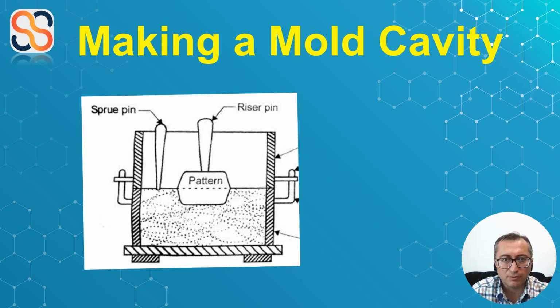After that, we remove the sprue and riser pins and create vent holes in the cope using a vent wire. These vents are very important. They allow gases generated during pouring and solidification to escape.